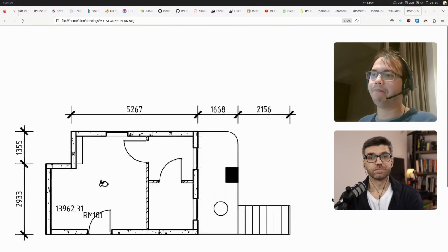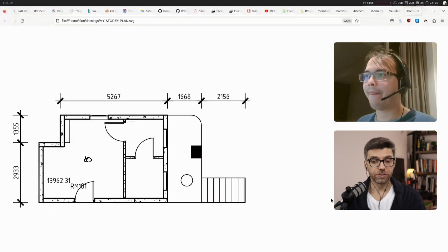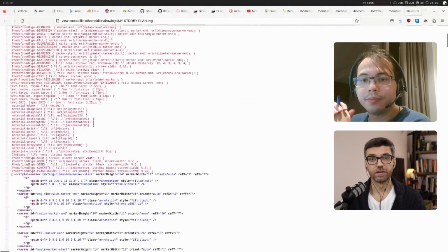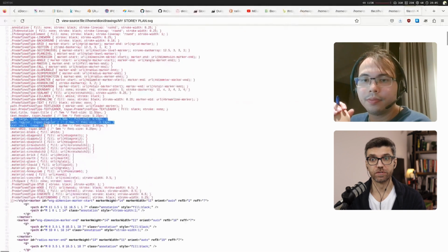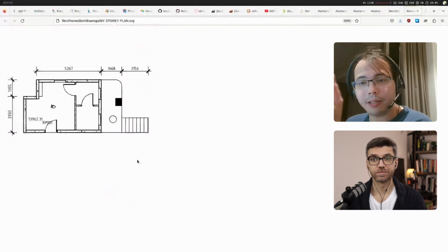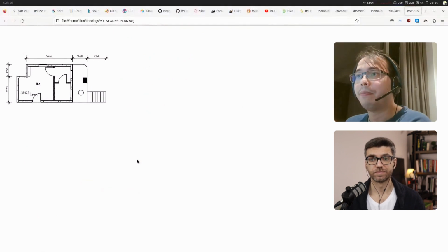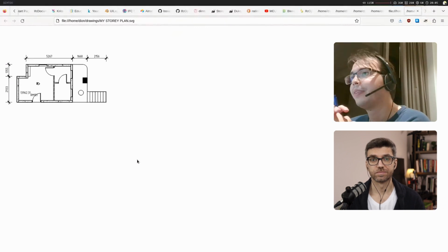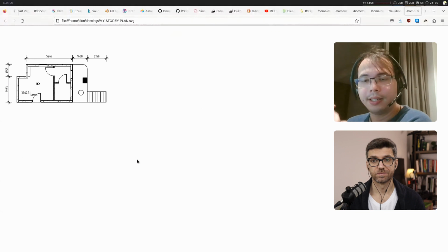Those assignments, CSS assignments, are they independent than a material that you would give of the IFC, or is it the same? So what happens is that your objects have a lot of data, right? It has names, materials, quantities, and so on, and properties. When you create a drawing, you say what data should this drawing contain. You might want to say, by default, it contains material data. That's pretty important for most drawings. It contains names or IDs if you want to have, and you can choose whatever data you want in there.